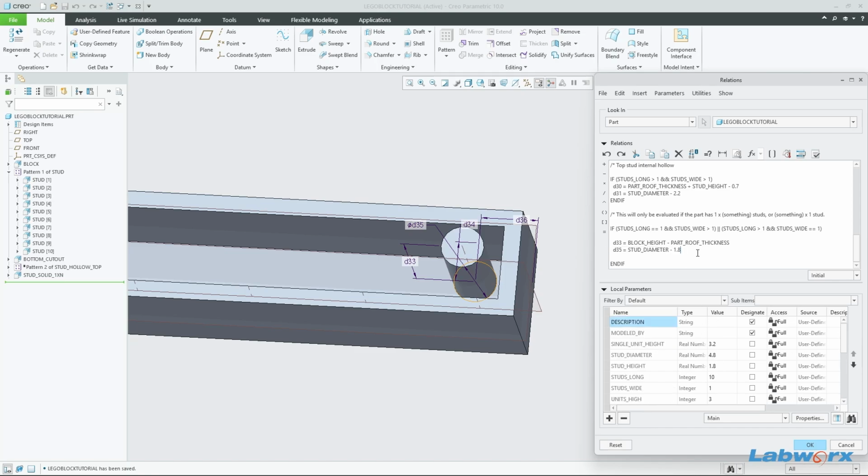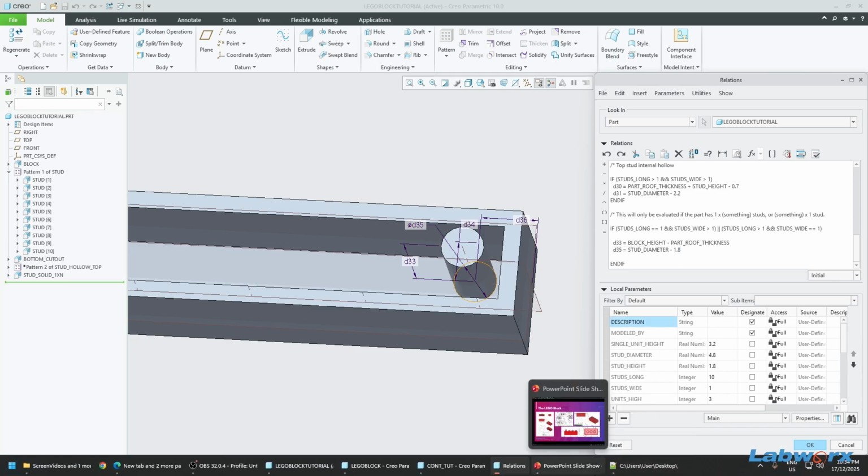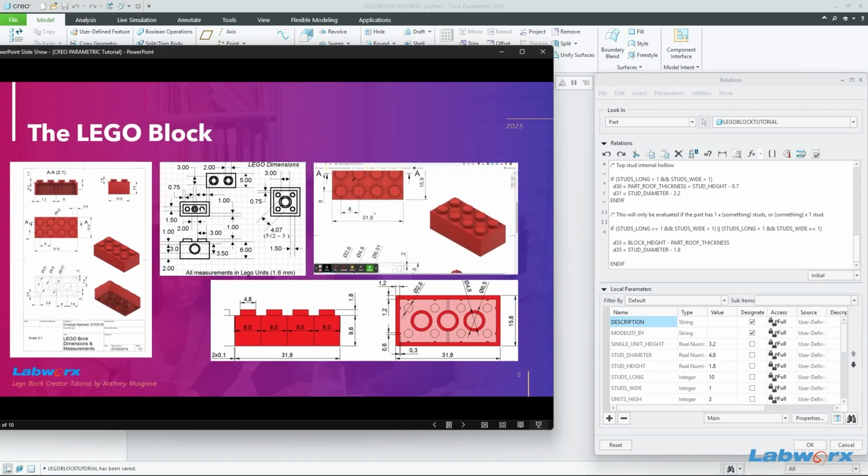Now that's because the standard, even though it says here on the slide that it's closest to 2 millimeters by the look of that, I have measured my parts here with calipers, and I'm getting close to 3. It's about 2.97. So I believe that this may not be accurate.